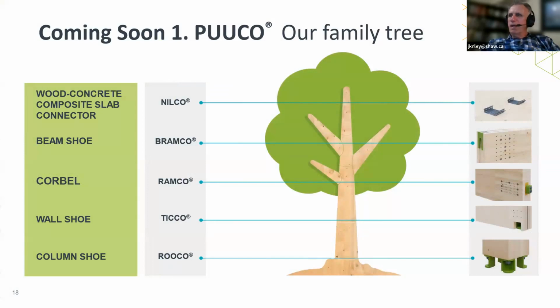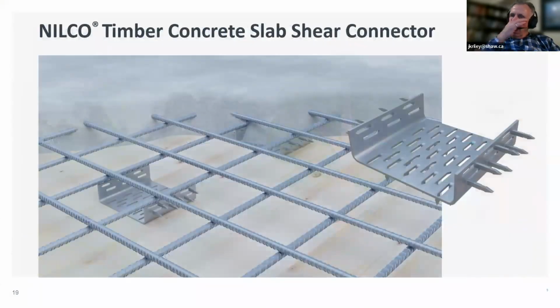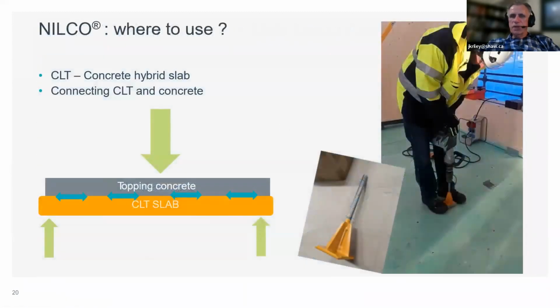So what we're doing is introducing a new connector here. Yes, it looks like a gang nail. What it is, is a specially designed plate that's hammered into place here to take the lateral load of your deck design. You can see here, the mesh is put on top of the connector, and the concrete's poured right on top. So this is a fast, economical system.